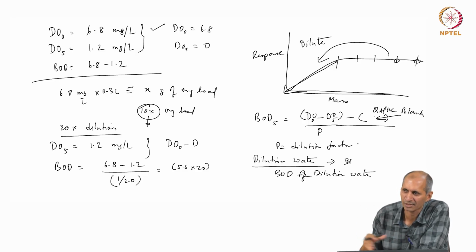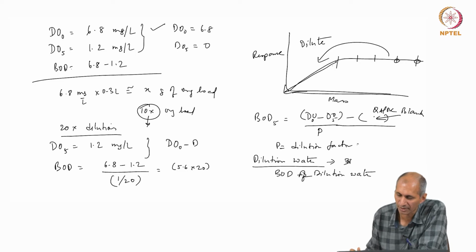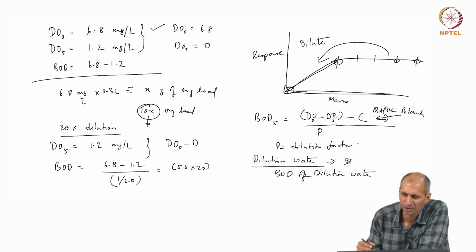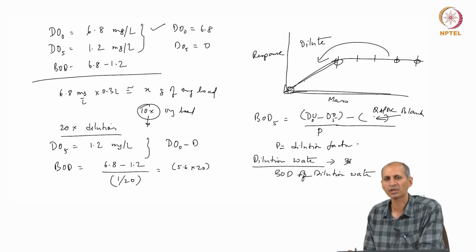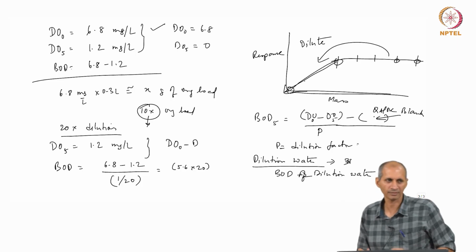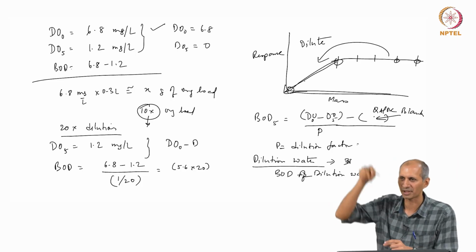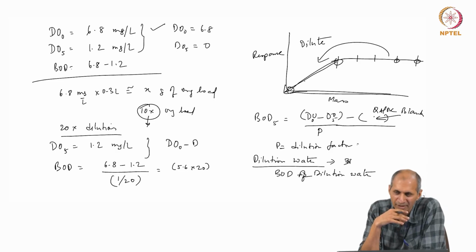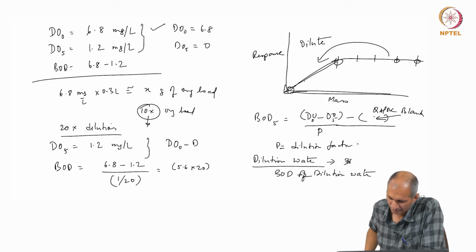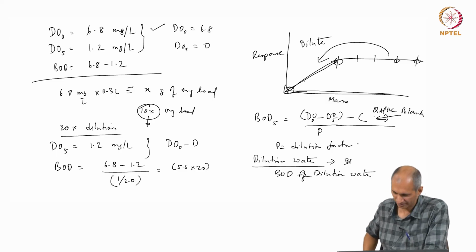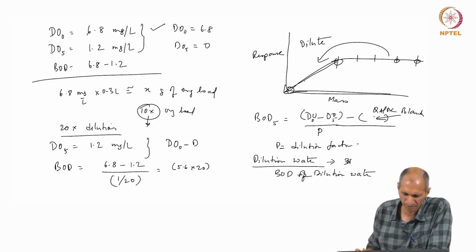It is a lengthy process, it takes time, this mass transfer of oxygen using nitrogen, and that is one end. So, you have a 2-point calibration. The 2-point calibration is very dangerous, but that is the best you can do as of now, because anything else in between is not stable. By the time you prepare everything, open the system, put the DO probe, it is not the same. So, it is a bit tricky. Any questions? This is just an overview of this.